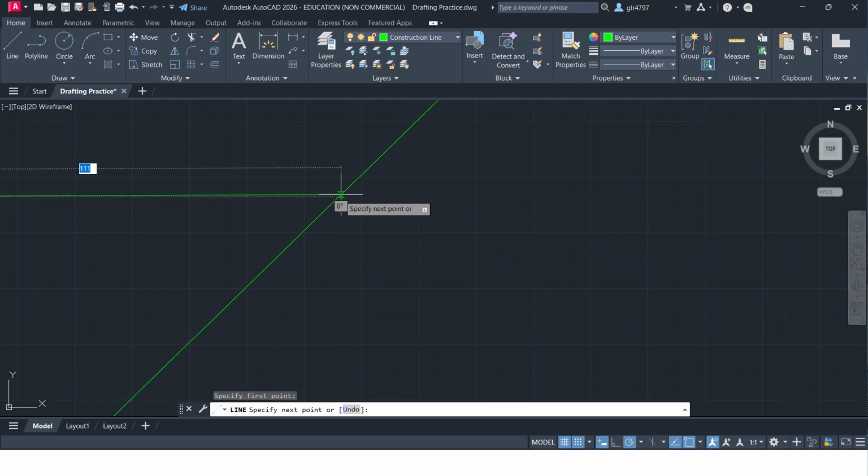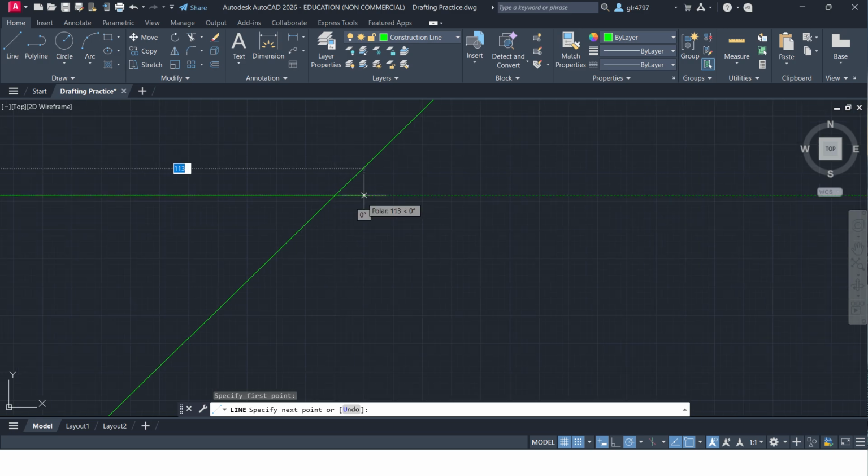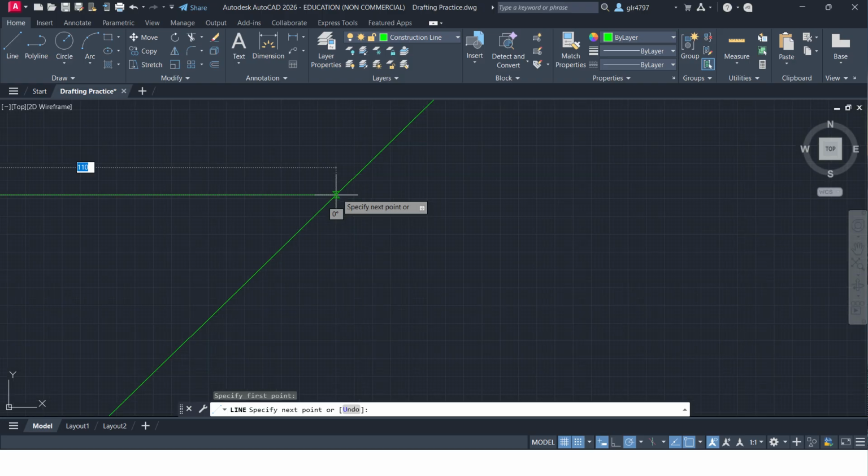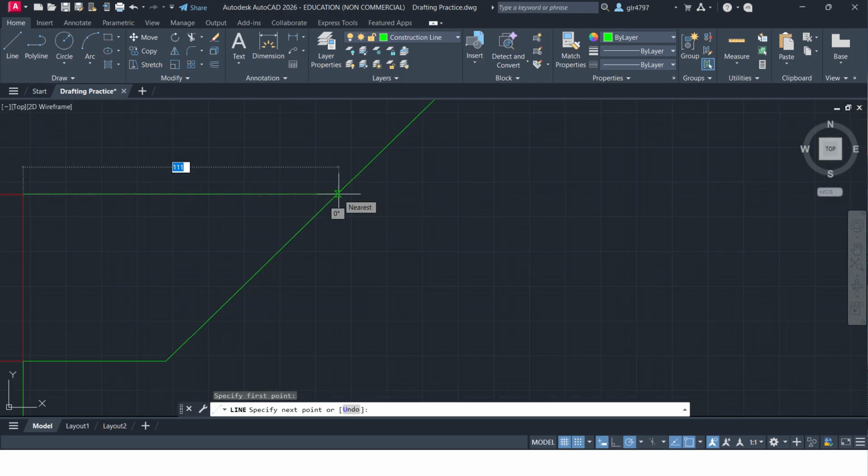I could make it go through. I could try to snap what I would like to do. It's hard to tell exactly where it is. Now, the snap settings may not make this super easy, because look, it's saying 0, it's saying 0. But notice how I'm technically changing the line, but the angle's not changing. So that's something you have to be very careful of, because it's still saying 0. Because we turned decimal precision off, or set it to the lowest level precision, you're not going to see what angle that truly is.